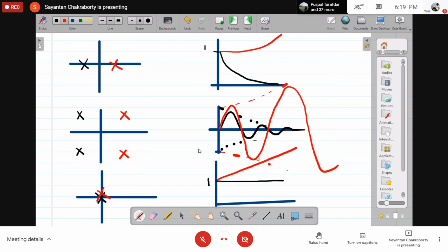And I've already shown you what happens if the poles are on the imaginary axis. So clearly, we can conclude that if the poles are in this portion, the open left half plane, they are stable. On the imaginary axis, it is stable only when there is a single pole. If there is a multiplicity of poles on the imaginary axis, then that system will be unstable. Otherwise, it will be a marginally stable system. So these poles therefore depict the stability of the system.